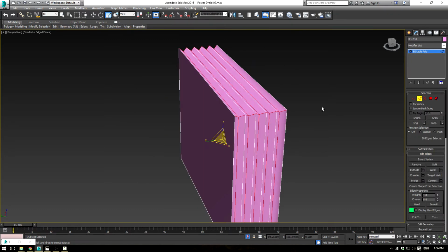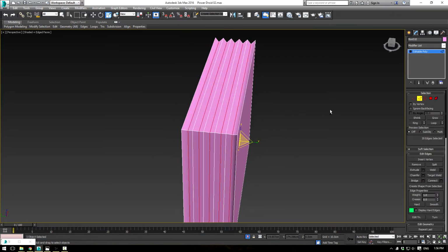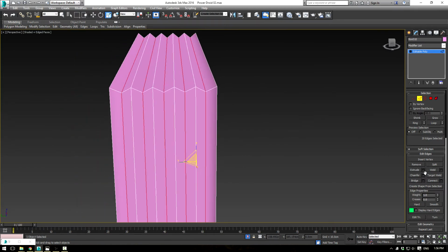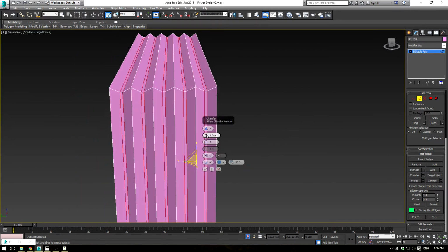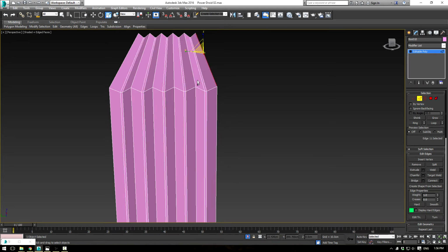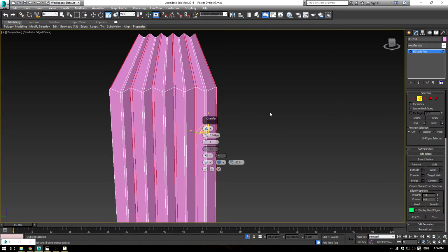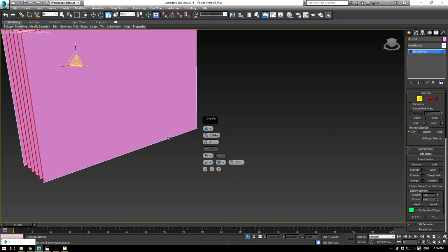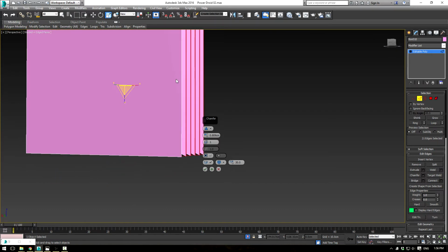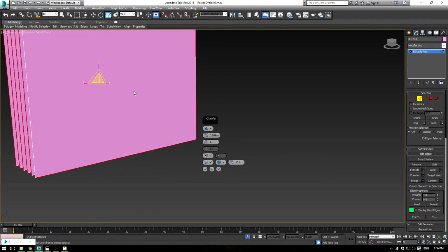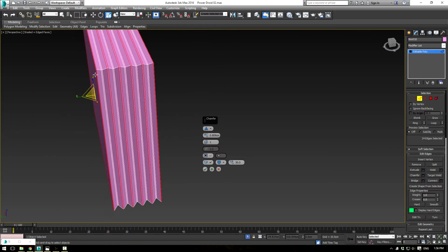Now control click your, now just get your lines again. Let's go ahead and chamfer these with sort of a smallish chamfer. Now grab all your other lines, okay, and go ahead and loop those and chamfer them. Looks like the outer edge here doesn't want to select, so go ahead and grab that selection. Alright, perfect.